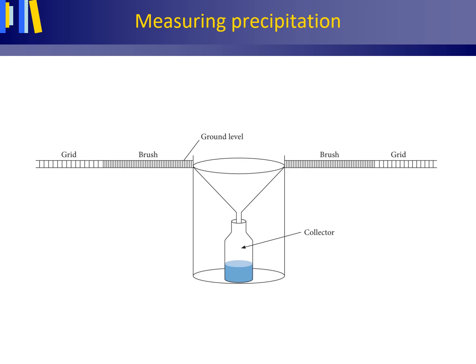To prevent underestimation of the rainfall depth, it is best to measure rainfall depth in a ground level rain gauge as shown here, where the top of the rain gauge is placed at ground level at the center of a grid and brush network that prevents the splashing of raindrops from the ground into the gauge's orifice. Another reason may be that a hydrologist usually wants to know the rainfall depth entering the soil rather than the rainfall depth at some standard height above the ground.